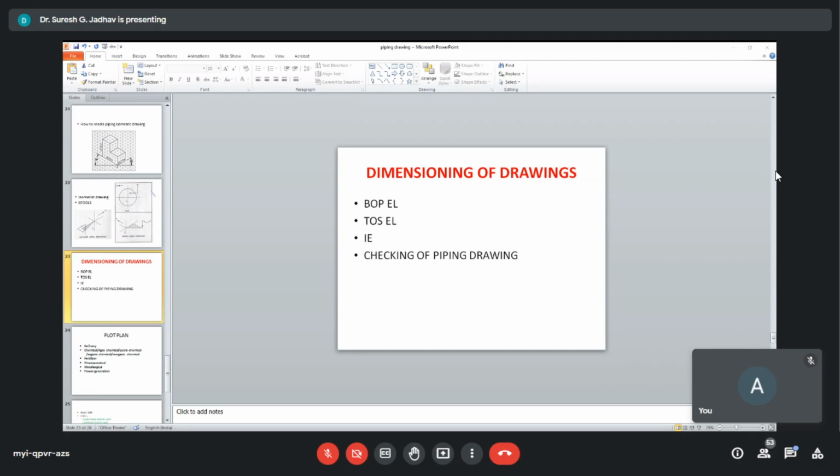Next is whether all stress analysis requirements are met or not. We have to consider these points for checking. Now next is adequacy of clearance from civil structure, electrical apparatus and instrument consoles. Next one is floor and wall openings and accessibility of operation and maintenance space and provision of dropout and handling areas. Foundation drawings and vendor equipment requirements.